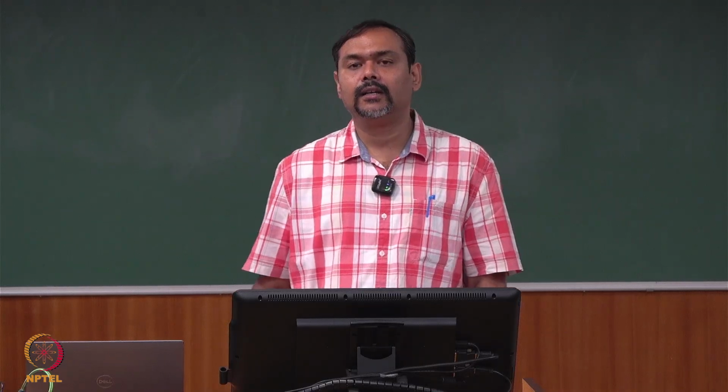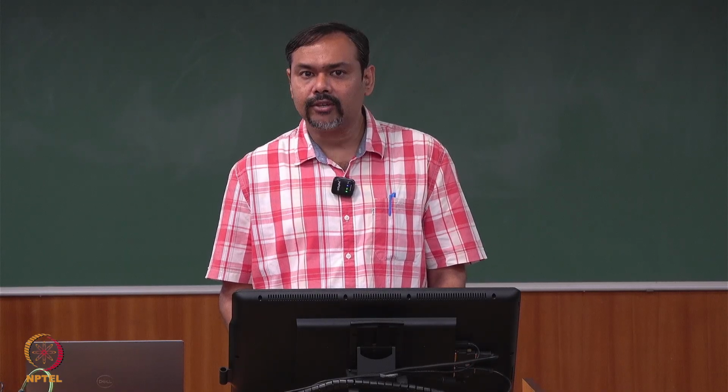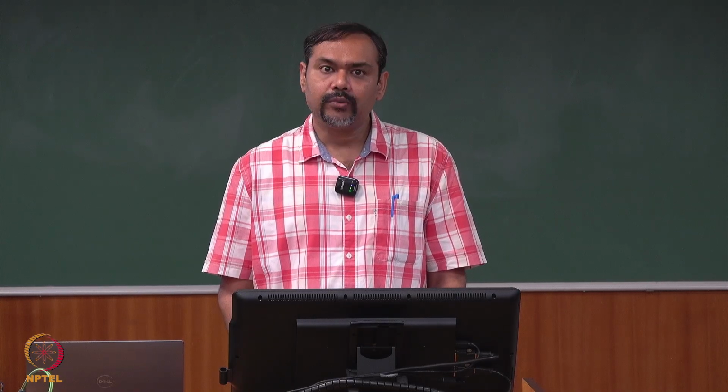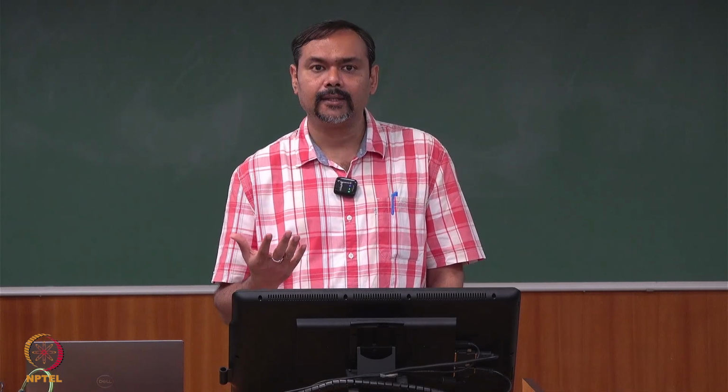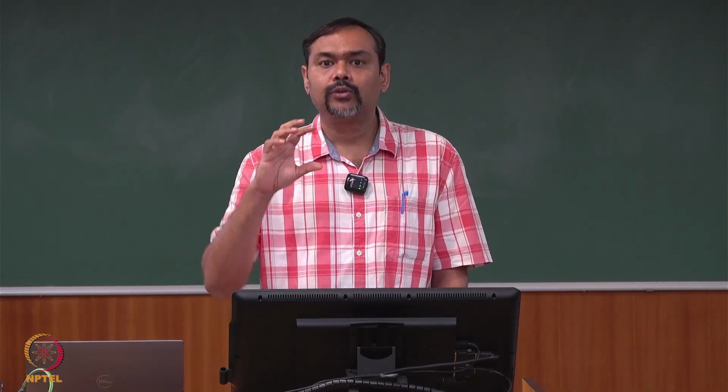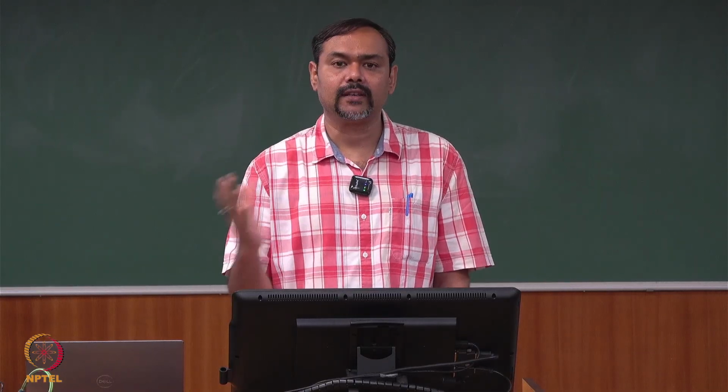With these two examples, we come to the conclusion of this part of the lecture, where we covered a basic introduction to space vectors, a little bit of space vector PWM, and most importantly how space vector PWM can be used to control the converter output voltage space vector, which can be adjusted to control the active and reactive power flow from the converter into the grid or vice versa.